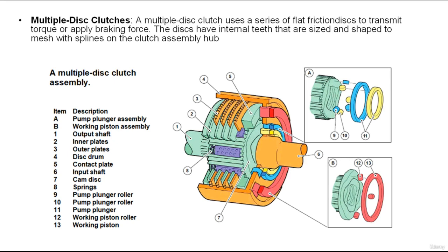The combination of friction and steel plates makes up the clutch pack. The clutch pack also has one very thick plate known as the pressure plate. The pressure plate has tabs around the outside diameter to mate with the channels in the clutch drum. It's held in place by a large snap ring. Upon engagement, the clutch piston forces the clutch pack against the fixed pressure plate.